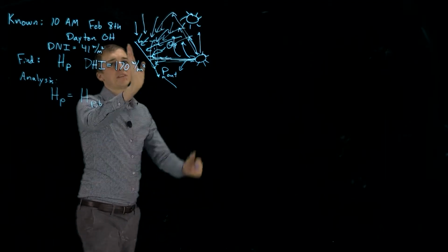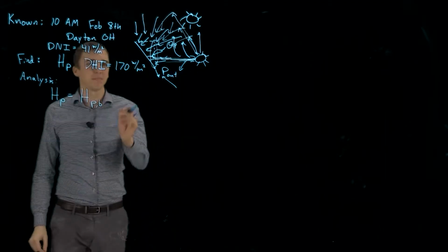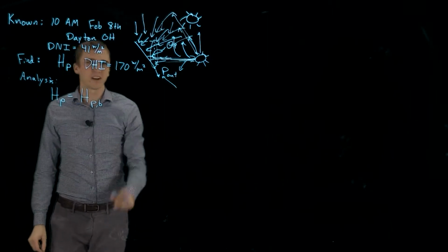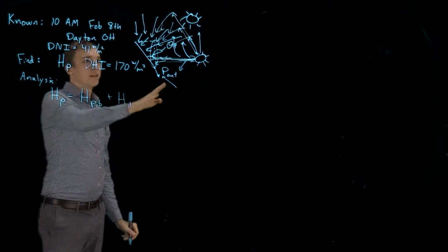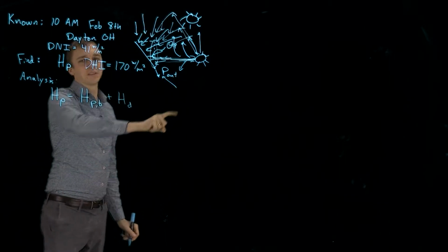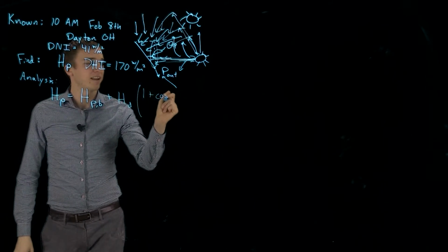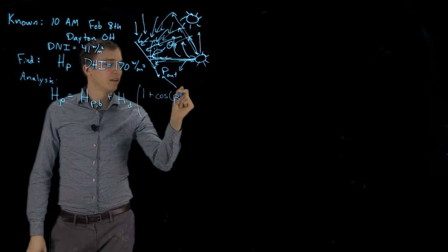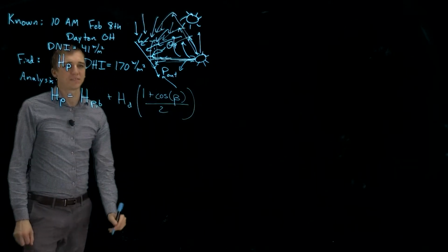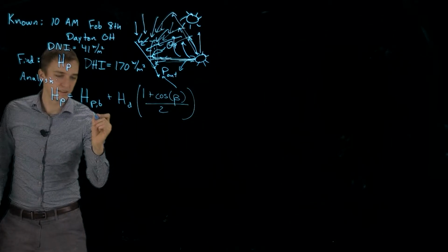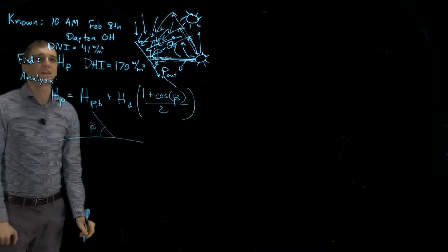Okay, so to find this panel incident heat flux, we find first the amount of heat flux that is hitting our panel normal to the direction of sunlight from just the beam component, the part coming directly from the sun, and we add that to the heat flux that is coming from all other angles, the diffuse component, and we project that area according to the tilt of the panel, where the tilt of the panel, if this is our panel and this is the ground, is this, beta.